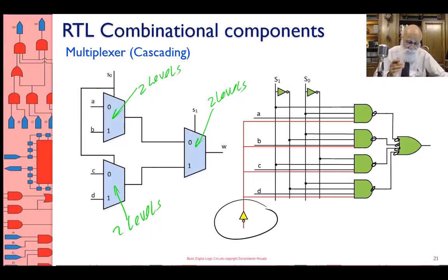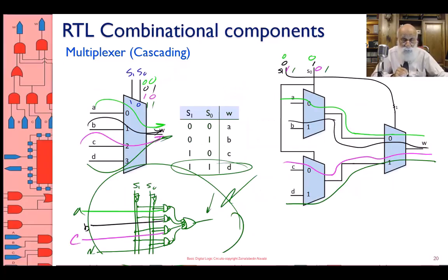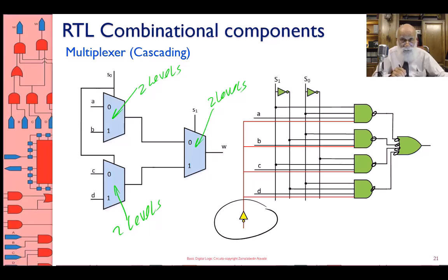So this circuit is no different than the circuit I'm showing in the lower left, except that I have an active low enable here. If the enable is 0, this is 1, and therefore the NAND gates are ignoring the input NAND and doing what their S1, S0 inputs tell them to do. But if my enable is 1, I get a 0 here. The 0 here will force all NAND gate outputs to become 1.